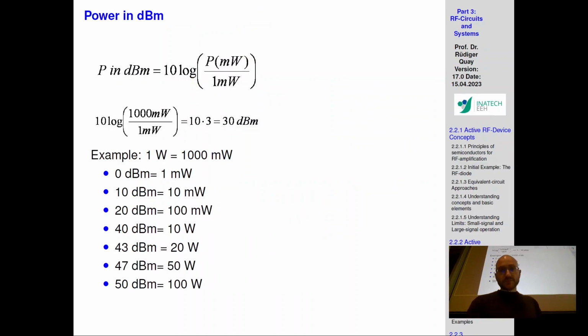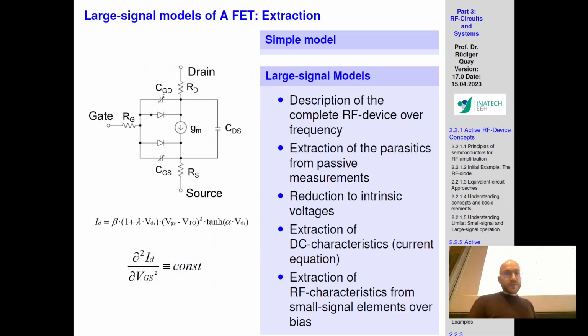And that is the issue: we are no longer dealing with only linear effects, we're also dealing with nonlinear effects. And what are the nonlinear effects? We're starting to deal with the problem that we have voltage-based parasitic capacitances at the gate, at the drain, at the source, or at the emitter, collector, and base.